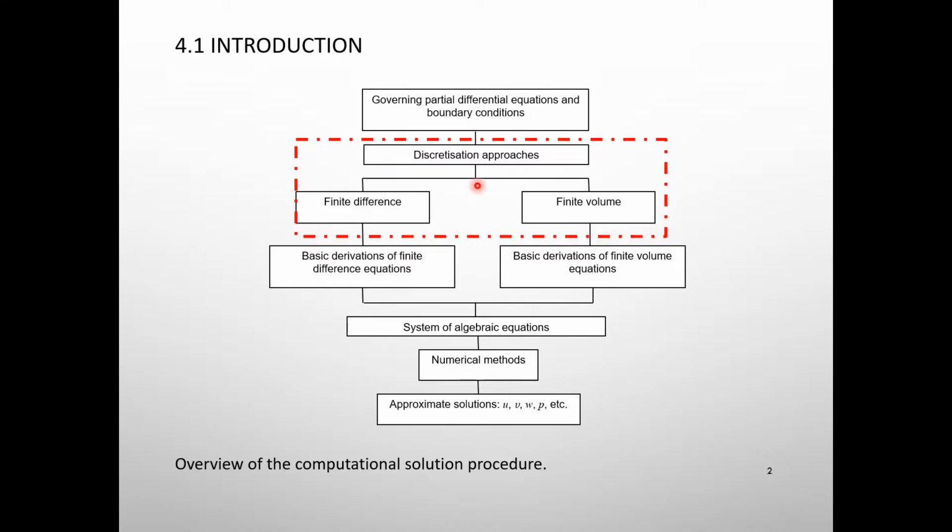Okay, this is the first stage that we are going to discuss for these techniques. The first stage involves the conversion of the partial differential equations, boundary and initial conditions into a system of discrete equations. This stage is commonly known as the discretization stage. The process of discretization can be identified through some common methods that are still in use today, which are shown here: the finite difference and finite volumes.